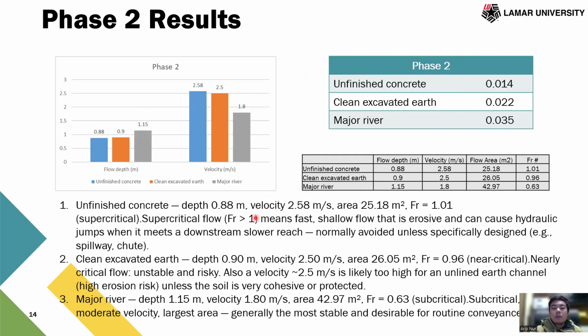This kind of result is normally avoided unless it's specifically designed for a spillway. So we need to modify the design to avoid supercritical flow.